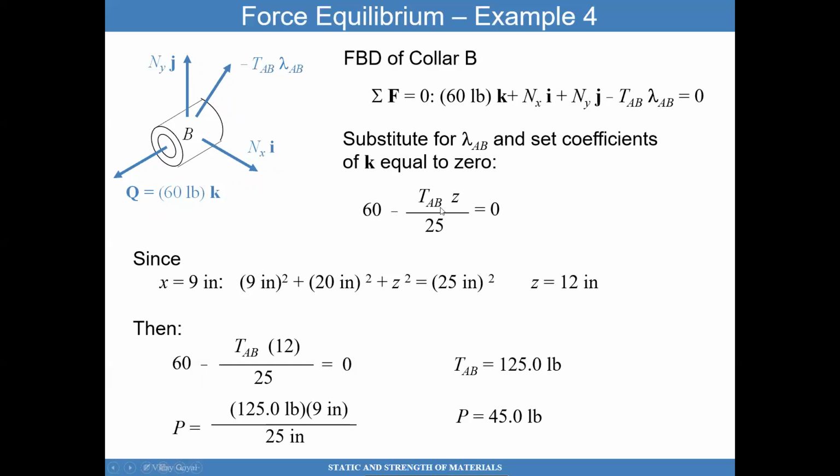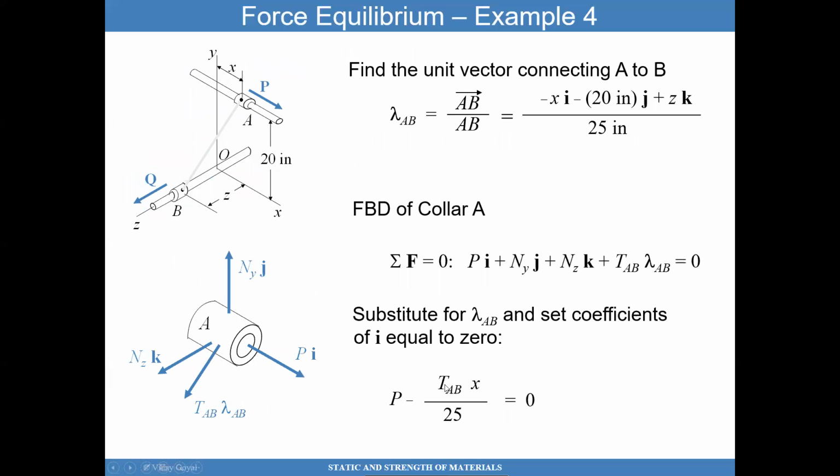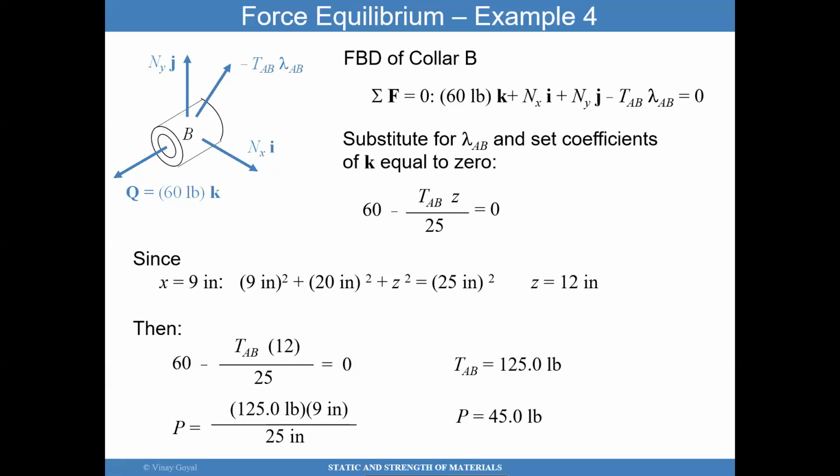And once I know the tension in that wire, I can go back here, plug it in here. I know what x is, 9. It was given to us. I can find the load P to maintain the system in equilibrium.